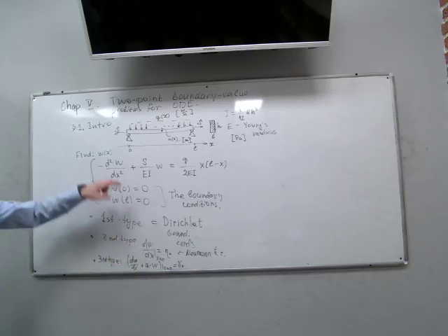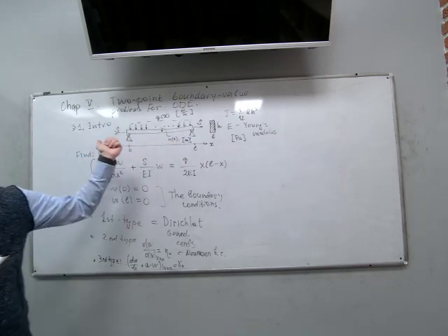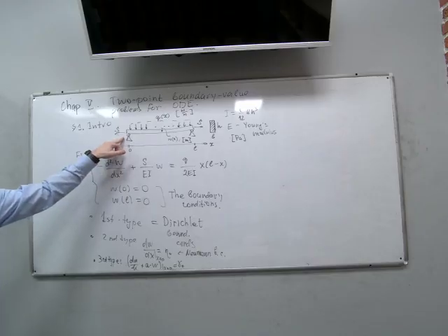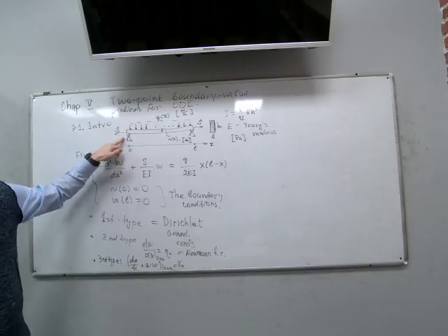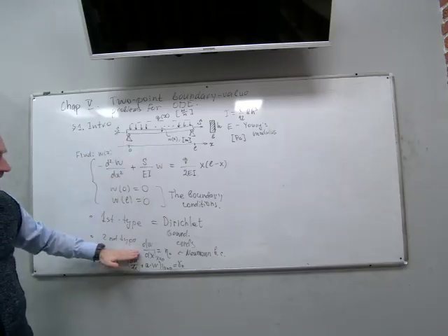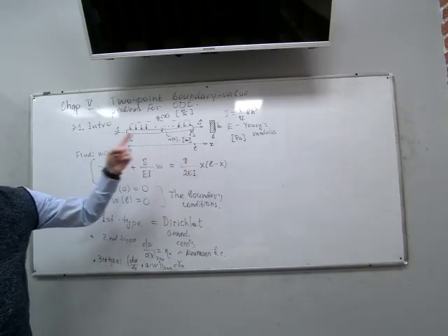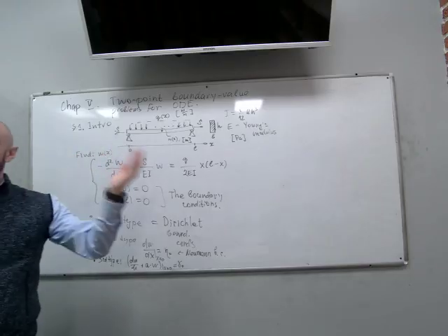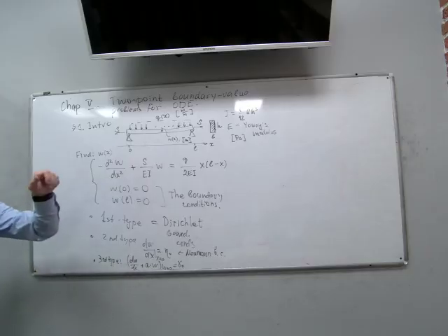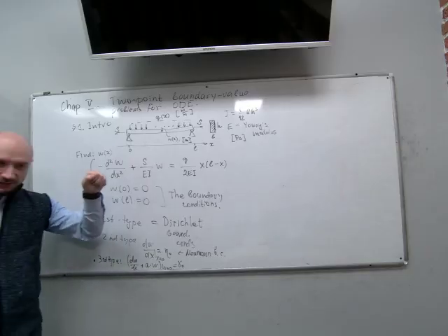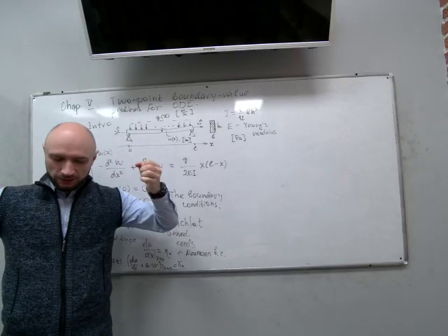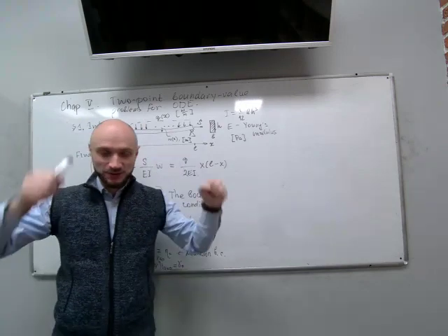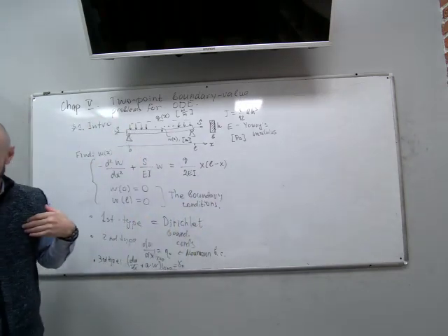If you define only the rotation moments on two ends, you do not define the position of your beam. If you define this condition on both ends, it will mean that you do not say where your beam is placed in space. You only say that you apply some rotative force to bend it, but where it happens in space is not defined.